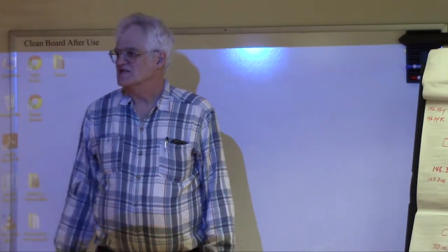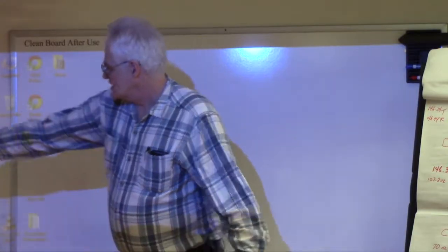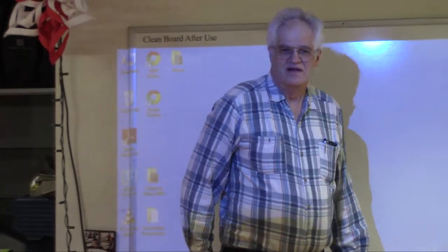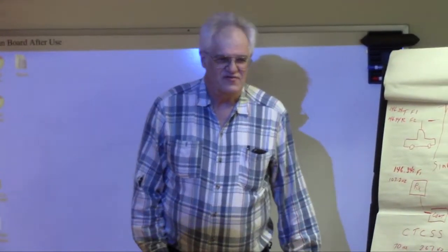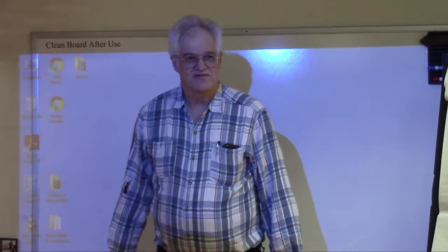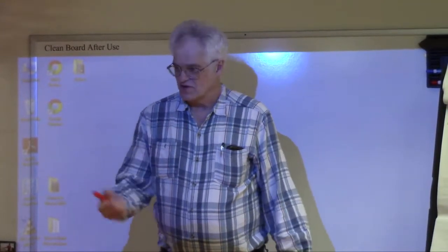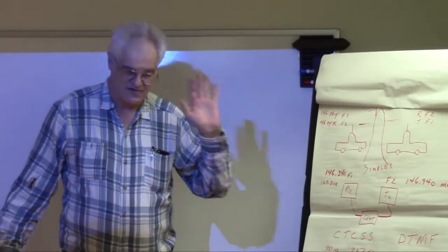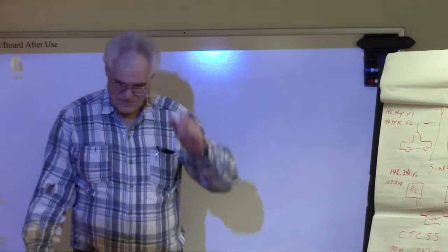And we use the exact same tones on a radio, on your microphone or on your keypad. In our case, typically you use it for functions like we can link and unlink various repeaters, and just by any radio knowing the code, punch it in, and there we go. So that's what we use DTMF for, basically for control functions.